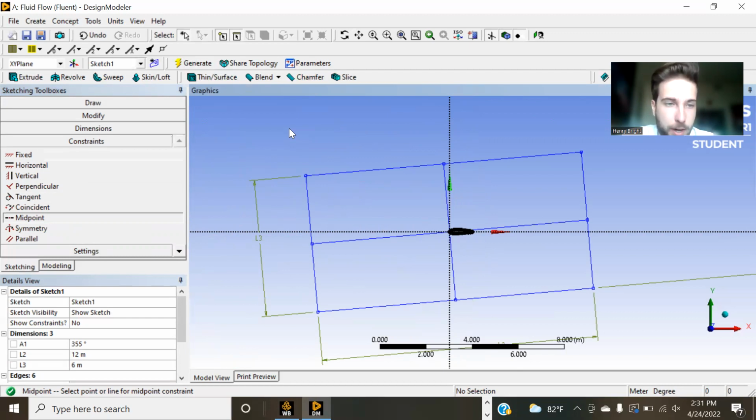So this is great. What I ended up doing in varying these is you do need to delete these lines. So you have to just redo them basically. It's very quick to do, but you could just delete them and then remake them when you need to change the angle of attack. But basically then this makes it super easy so that every time you want to run a new angle of attack, you just have to come back into your geometry and change the angle.